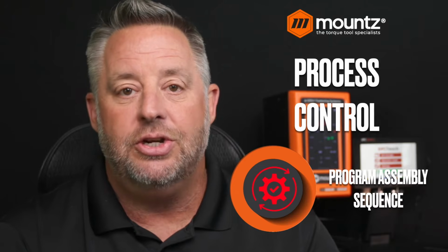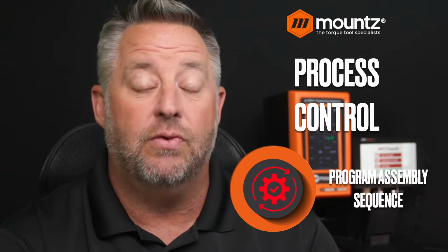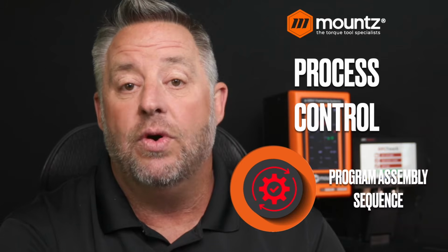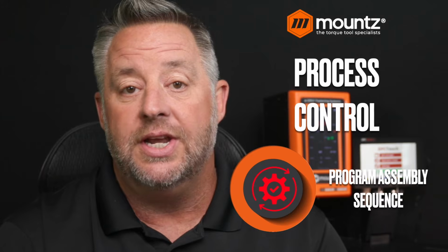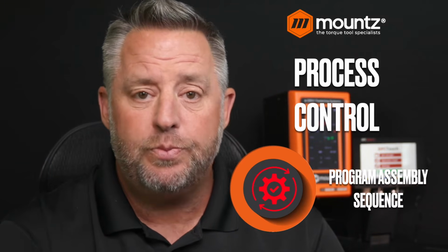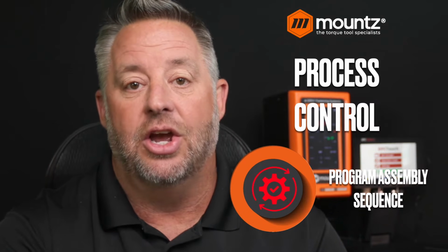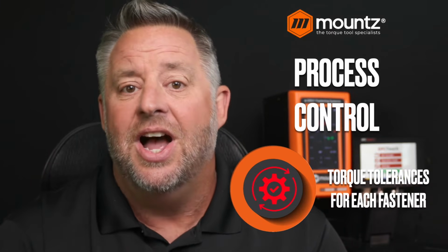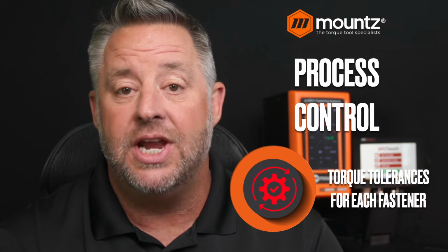Because we have the ability to use different presets with different torque values and different characteristics for that particular preset, we can then utilize that for the assembly process, where we can monitor where the tool is and change the torque for that automatically within that sequence process to make sure that we get a good, efficient assembly process, that we can then again monitor tolerances for torque at each of those fastening locations.